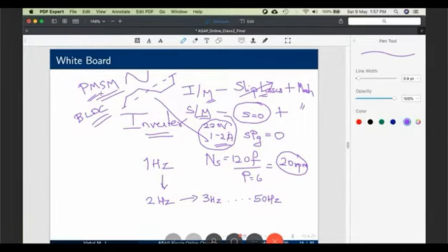All right, thank you. Now we have seen the true synchronous mode. What was the reason for these troubles we face in true synchronous mode? Omega is not equal to omega r during transients, and this was the reason we had some problems in the true synchronous mode of operation.